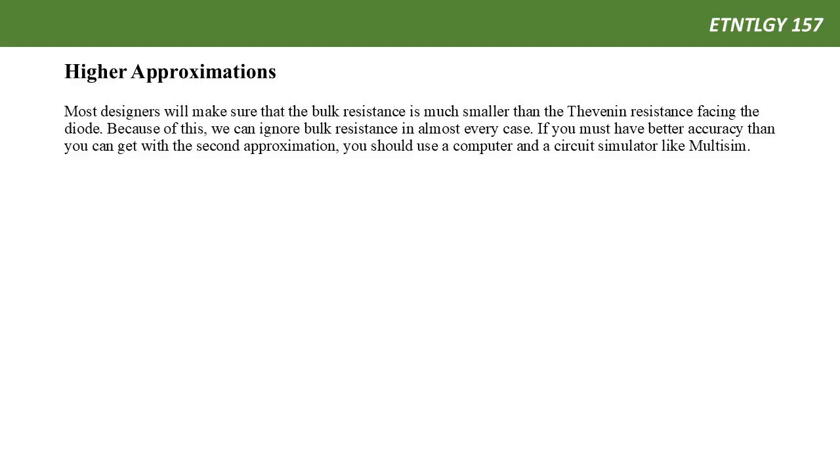Most designers will make sure that the bulk resistance is much smaller than the Thevenin resistance facing the diode. Because of this, we can ignore bulk resistance in almost every case. If you must have better accuracy than you can get with the second approximation, you should use a computer and a circuit simulator like Multisim.